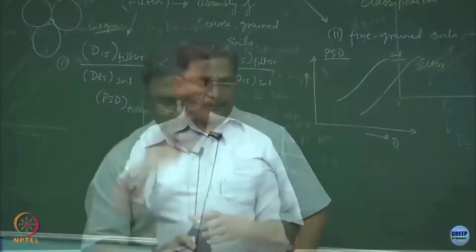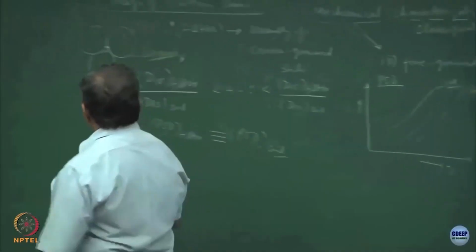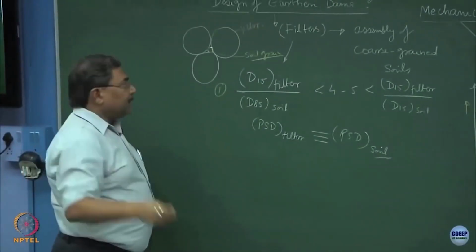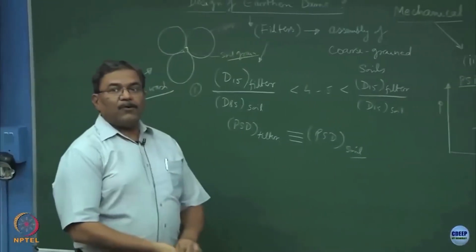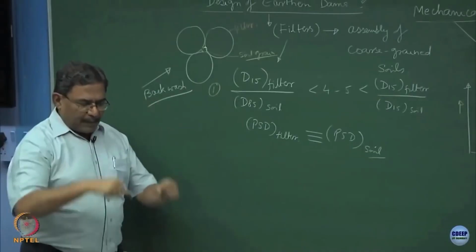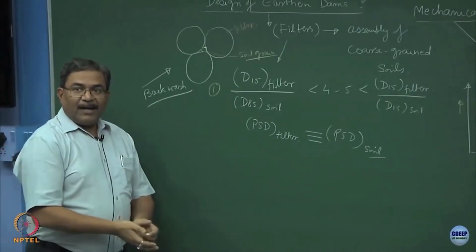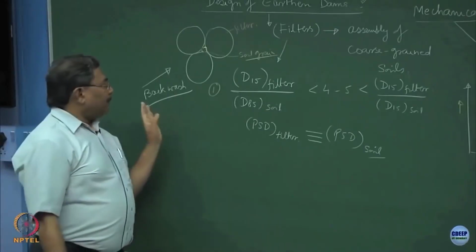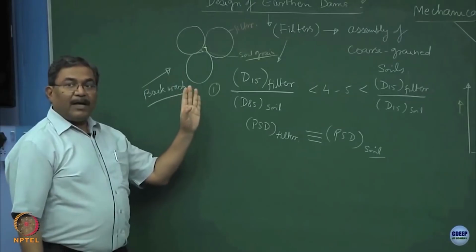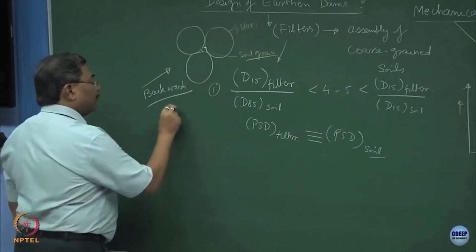Anything else? Yes. The filter which we use for water purification, once the dust or the dirtiness is trapped in the filter, is there any process to remove the dirt, or is the filter just wasted? Very good. Excellent question. When I am teaching seepage analysis, if I do backwash, alright. So, what am I going to do? If I pump, let us say, some fluid inside the filter, and force these finer particles to come out of the matrix, it is a sort of a washing, clear. So, by applying back pressures or by applying backwashing, I can clean up the filters. So, you can rejuvenate them. Read more on the net about this.